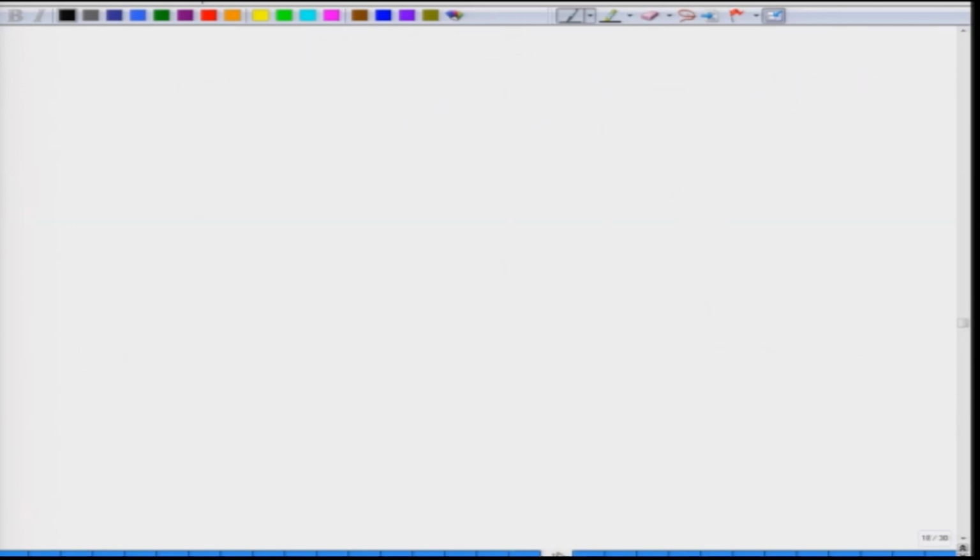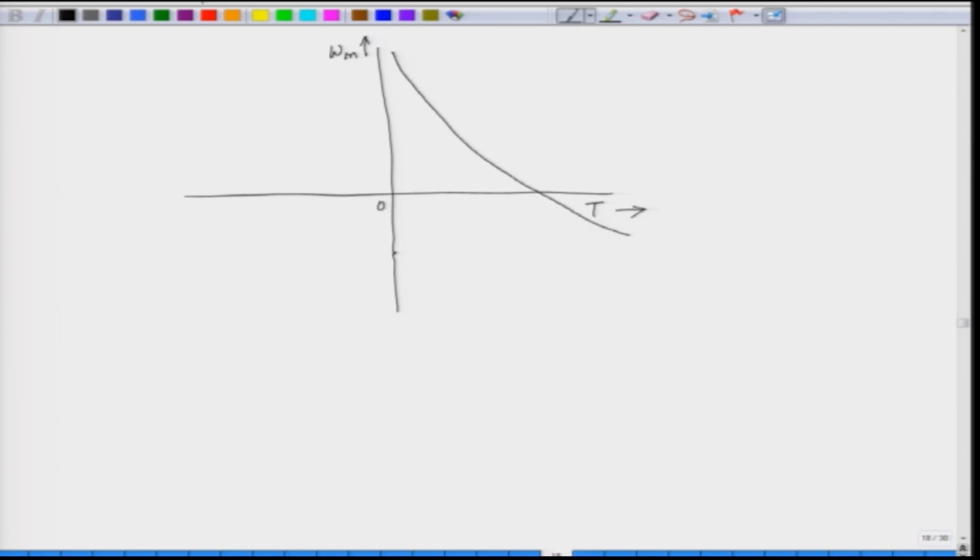Now, if you see the speed torque characteristic of a series motor, we have speed on the y axis and torque on the x axis. This is how we plot the speed torque characteristic, and for the reverse motoring, this is our speed torque characteristic.